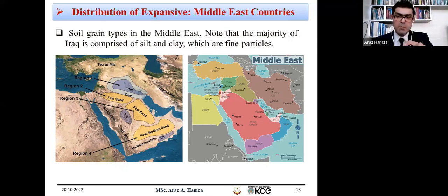If you remember, I said if the soil contains silt and clay, there's a possibility of a problem. But now you need to deal with it more, because the clay content does not mean that it is 100% expansive soil. You should go through the mineral composition. If the mineral is montmorillonite, that means expansive soil.